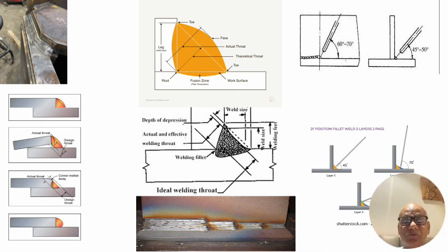the amount of force from one single tack of 3 millimeter length by 3 millimeter fillet can take a few hundreds of tons of load, or can create a shrinkage force. And that's why even a very thick plate, starting from the fillet, bends. It either goes this way or this way depending upon where you are going to do the fillet.